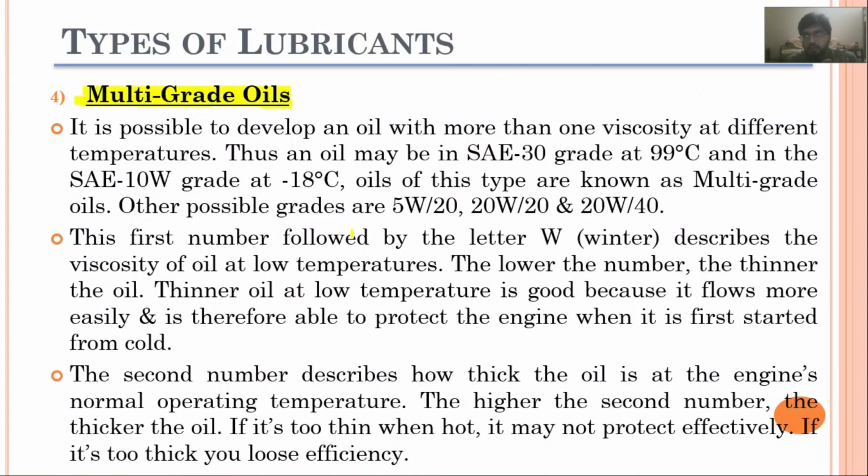Now you have a clear idea regarding SAE 5W and SAE 20 grade oils. As the name suggests, this oil would act like one grade of oil at lower temperature conditions and like some other grade of oil in summer conditions.